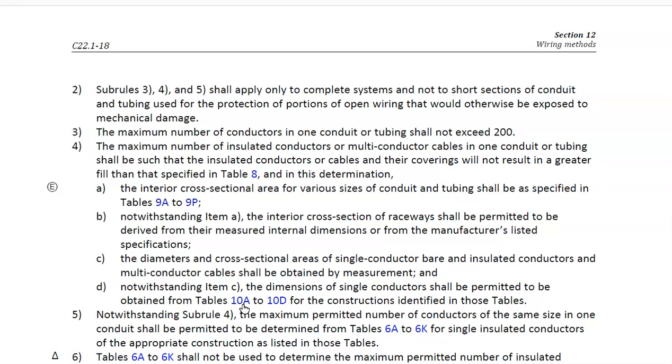Example number 4 would allow you to take a look at your Table 6s, right? Because it's all one size. Your example number 4 inside of the book talks about 8 number 12s. So you could use those Table 6s and find the correct type of conduit and take a look inside of there. And so, yeah, that's easy enough to do. Or the other way, you could also still calculate those things longhand. So they do give you a longhand one that you could do as well. Either way, when they're all the same size, use either one. If I'm in a rush, I'll use these ones.